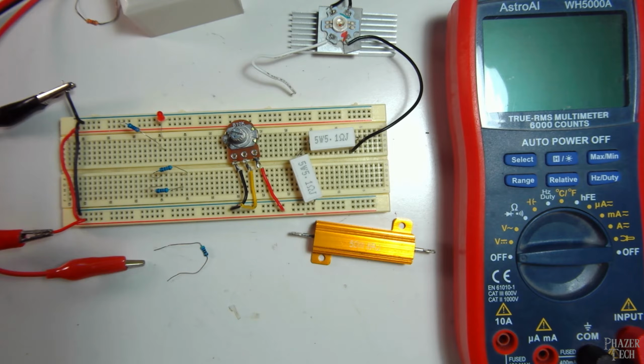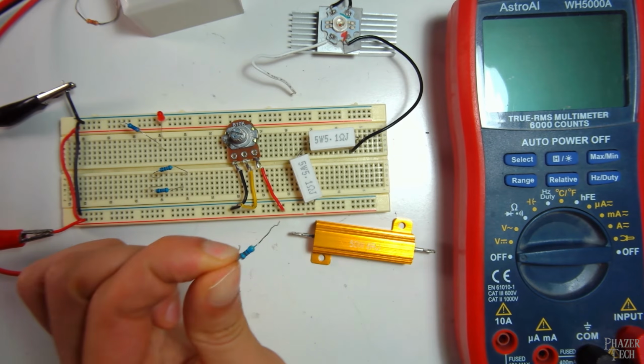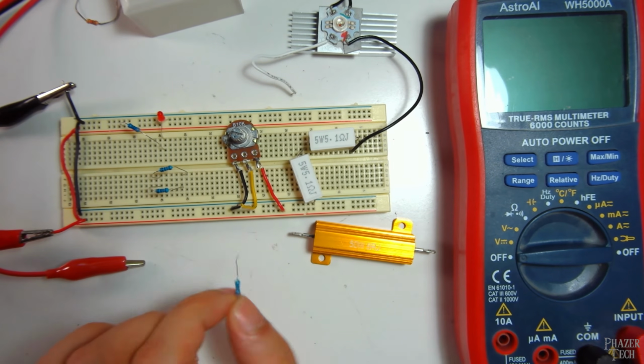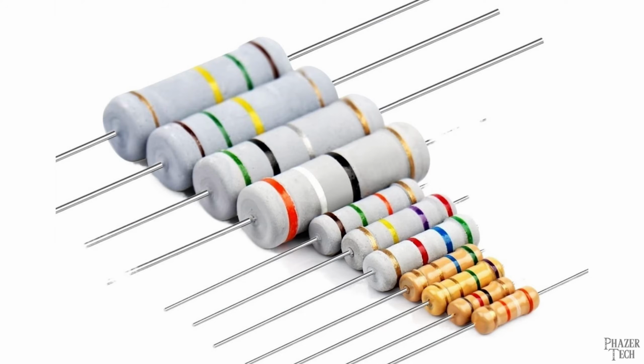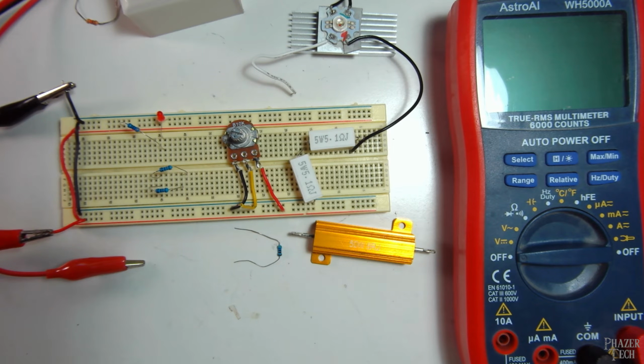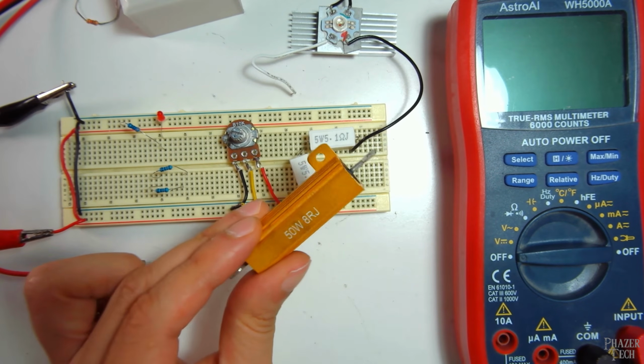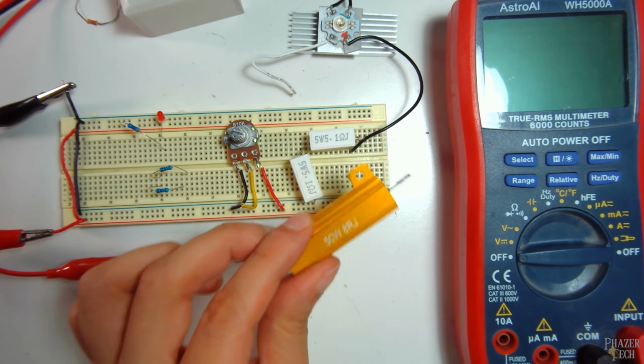The majority of resistors you'll use in a typical project will be these tiny quarter-watt resistors, since most signals don't use much current. But occasionally you will need resistors that can handle more power. You can find half-watt, 1-watt, 2-watt, and 3-watt resistors that look similar to the quarter-watt ones, but are just larger in size. But their appearance starts to change a lot when you get into the higher power ratings. These white ones here are cement resistors that can handle up to 5 watts, and this bronze one has a metal casing that can handle up to a whopping 50 watts.